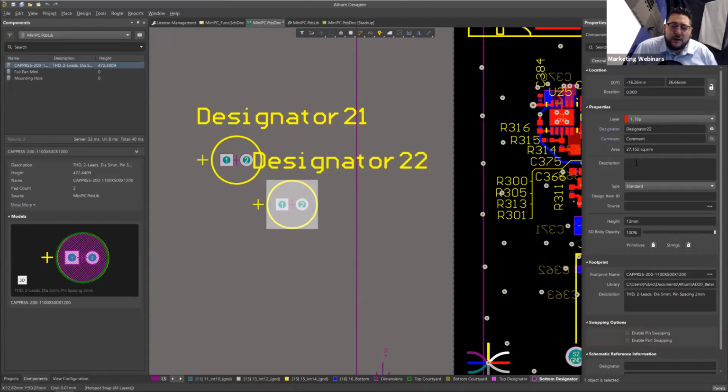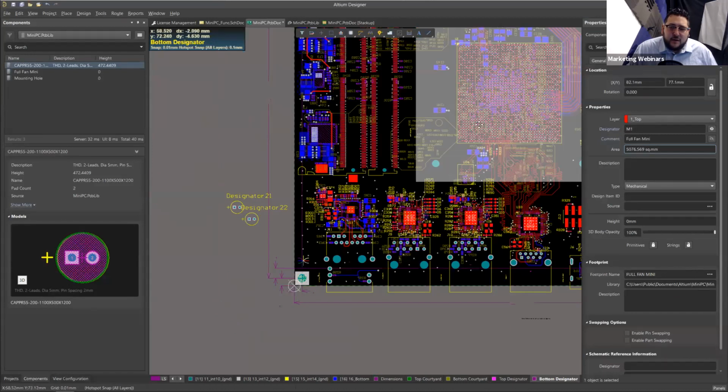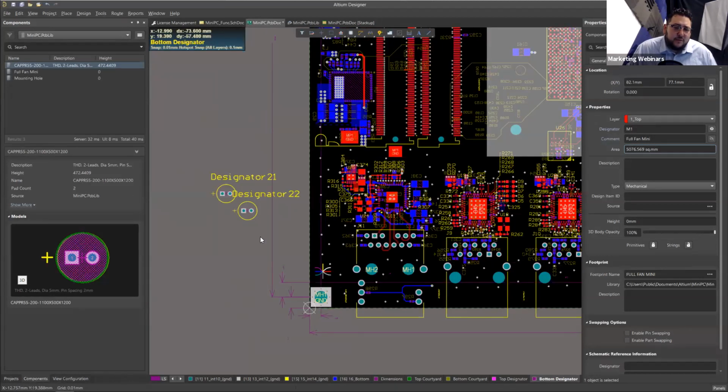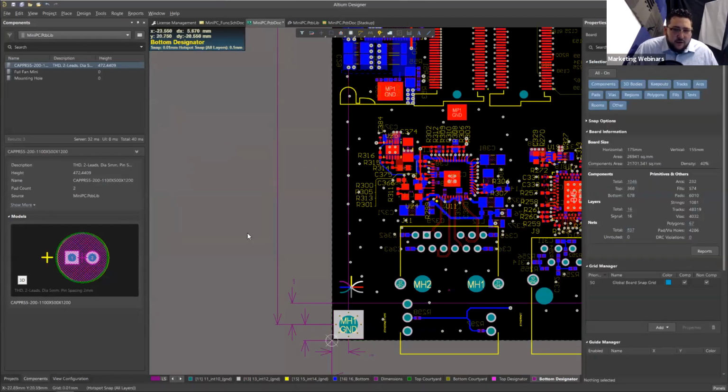If you don't want to use that item in your design for board density, all you have to do is put 0, and it will no longer calculate that into the overall design. For example, if this design has a big heat sink in the middle and we wanted to not take into account the area of this fan, we could make that 0, and it will change the board density of this whole design.